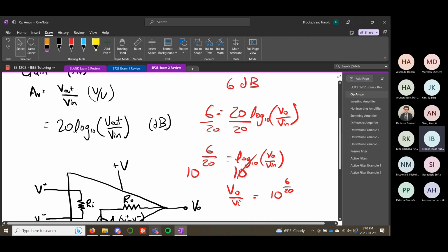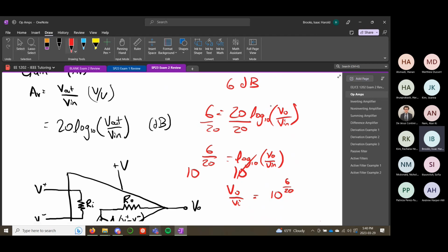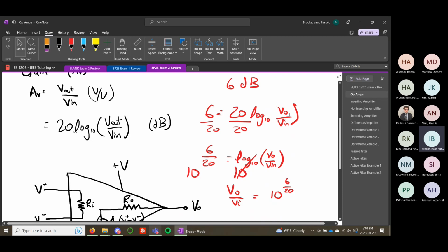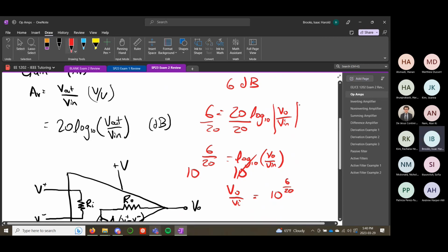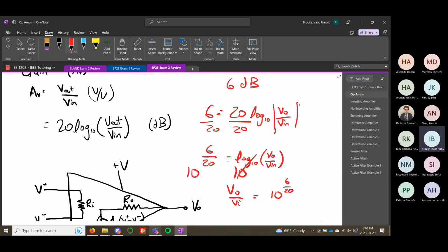That's a good question. A lot of times when you see that, it'll be an absolute value. I should probably put that here. When you're talking about amplifier circuits, you're not really concerned about the positive or the minus. You're more concerned about the magnitude of the gain. So for your ratio Vout over Vin, this one's nice because it has information about the magnitude: if it's 0.5, then that's a half, or if it's 10, that means your output is getting multiplied by 10. But it also can have a sign on it, a plus or a minus, and that tells you whether it's inverting or not.